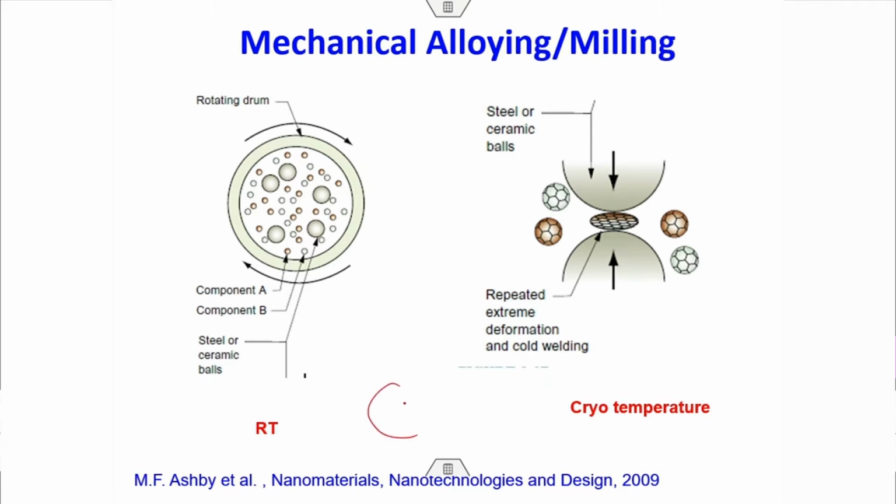You can always generate a lot of defects inside the grains, and these defects slowly align. These defects, which are nothing but dislocations, can align and produce such nanocrystal grains easily. These grains are initially separated by small angle boundaries, correct. So they then slowly become high angle boundaries.